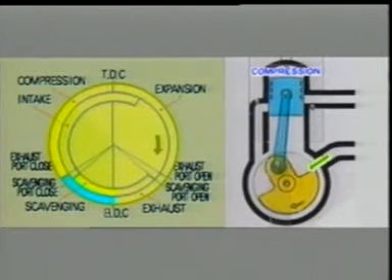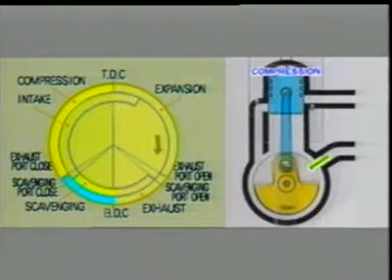When the piston reaches TDC, the vacuum is no longer created in the crankcase chamber. The reed valve then closes and intake is completed. Note that the reed valve intake system requires special intake timing. The opening and closing of the reed valve is determined by the speed of the revolution of the engine and the inertia of the mixture taken in.